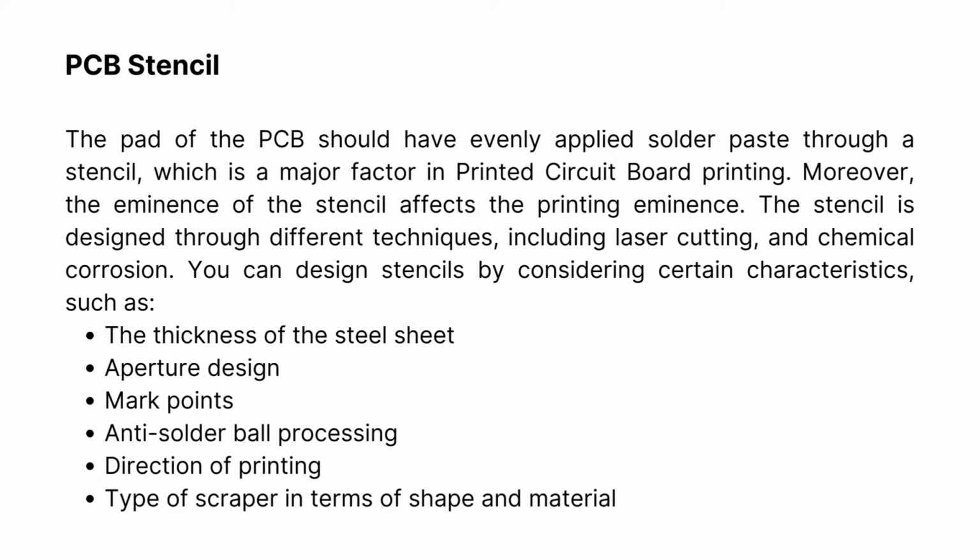The stencil is designed through different techniques, including laser cutting and chemical corrosion. You can design stencils by considering certain characteristics, such as the thickness of the steel sheet, aperture design, mark points, anti-solder ball processing, direction of printing, and type of scraper.